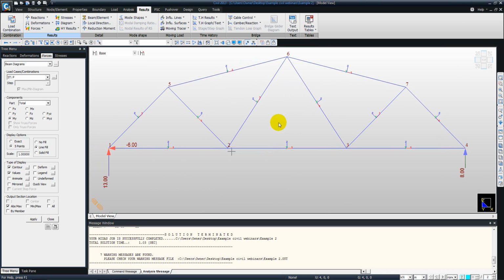So it shows you different colors for the axes, the red being the x-axis, which is the longitudinal axis for a given element. The axial force will act along this axis, so any kind of tension or compression force will act along the x-axis of a given element. So we need to select fx to see the results for axial forces. So select fx here.